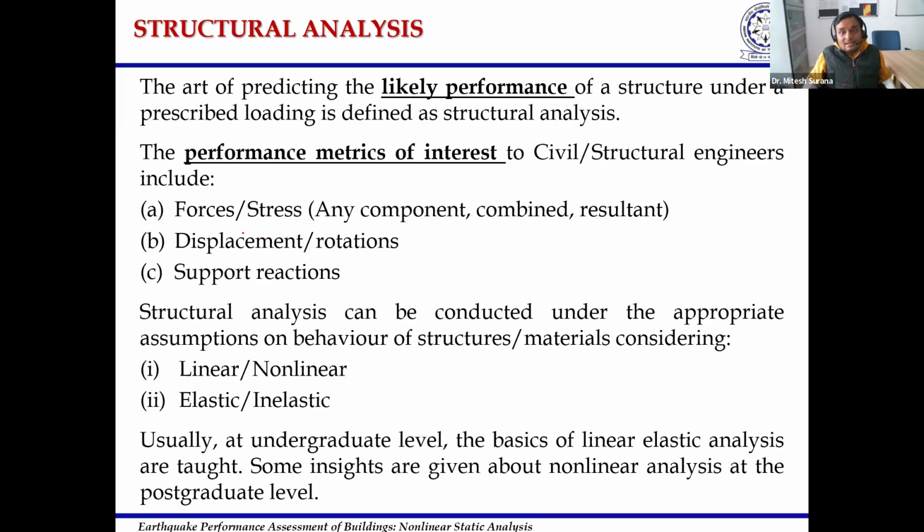Similarly, what do we mean by elastic analysis? Elastic analysis is that the material or the system which we are analyzing, in that particular system, the loading and unloading follows the same path. If this assumption is violated, then that type of system is classified as an inelastic system. So the primary assumption when we study any type of structure, a beam, frame, or any other structure, is of linear elastic behavior of the structure.